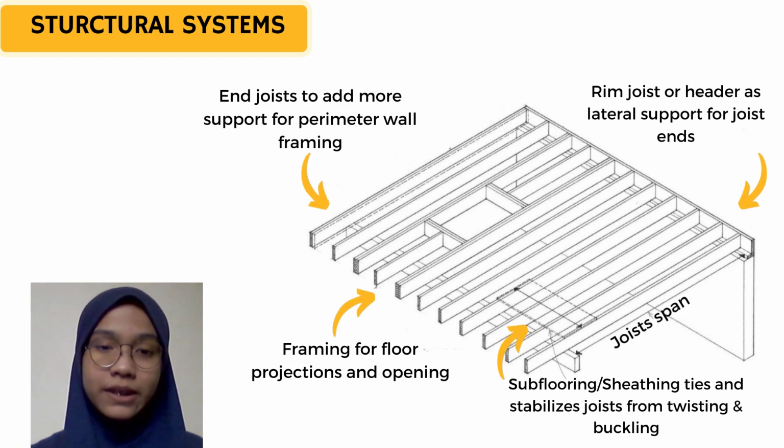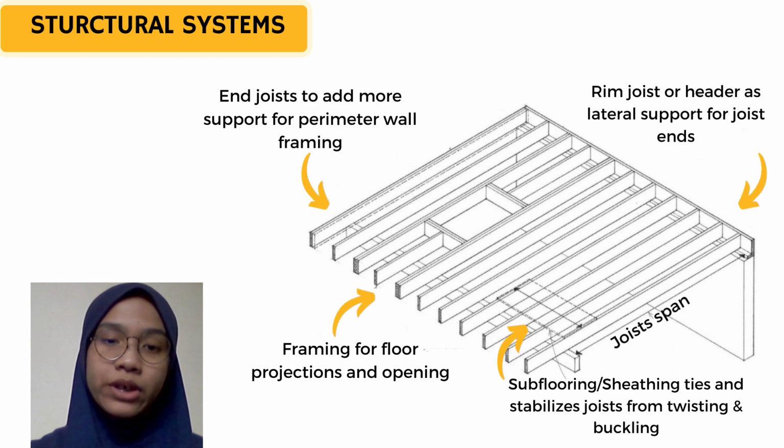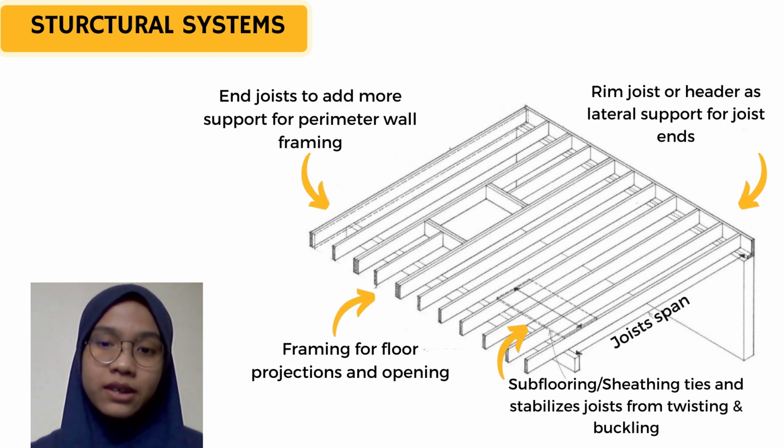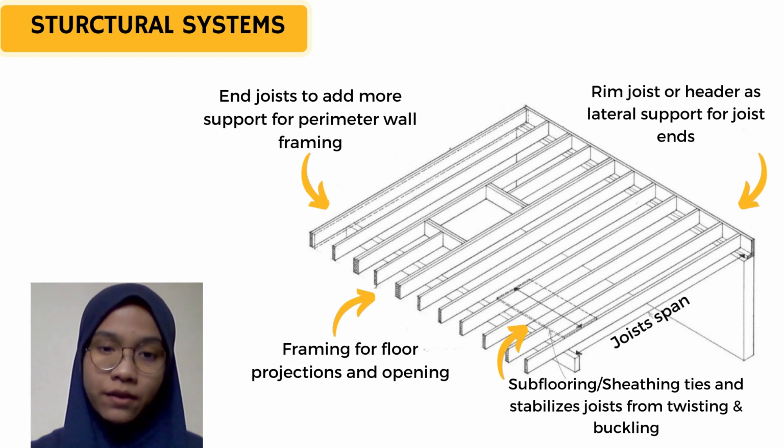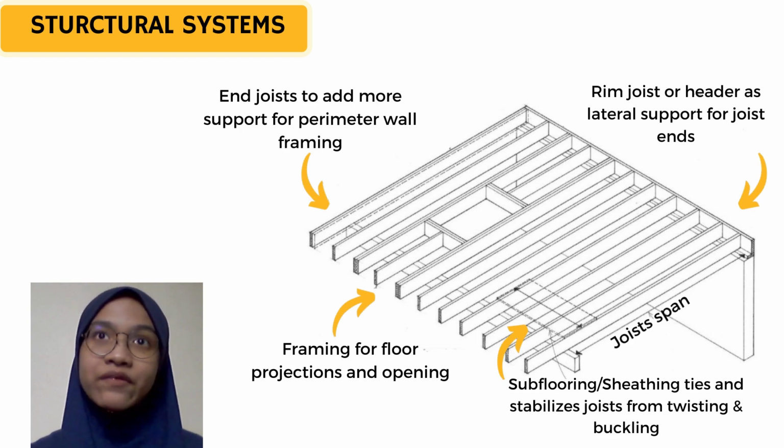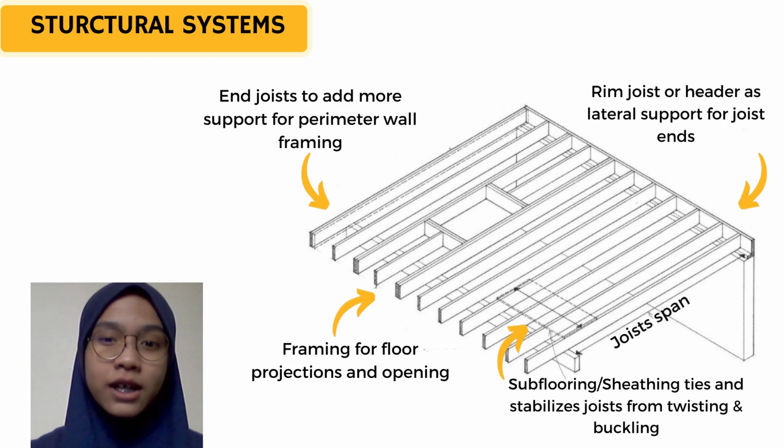The first one, we will explain how the floor joist, which is the wood plank, is evenly spaced and fastened with steel plates. The supporting beams are placed in between each of the floor joists so that the joist wouldn't move around, and this gives more security to the joist itself.